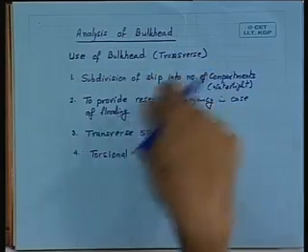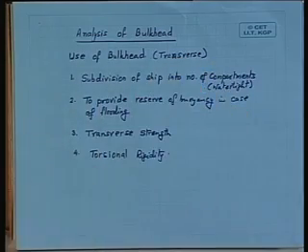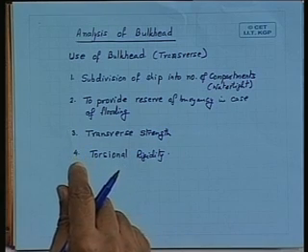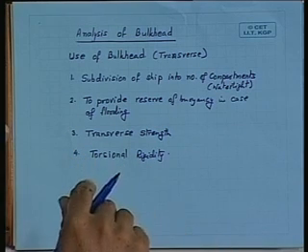And the very first, that subdivision of the ship and providing reserve buoyancy implies that when the compartment is flooded, that means there is water inside, and water will try to exert pressure from inside to all the 5 parts, namely the 2 sides, the 2 bulkheads and the bottom.